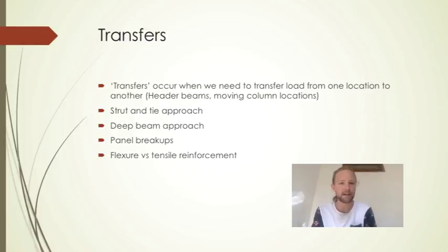Also, the difference between flexure and tensile reinforcement. So tensile reinforcement is for the strut and tie approach, which we'll cover, and if you design it as a deep beam, the reinforcement's going to be in flexure.